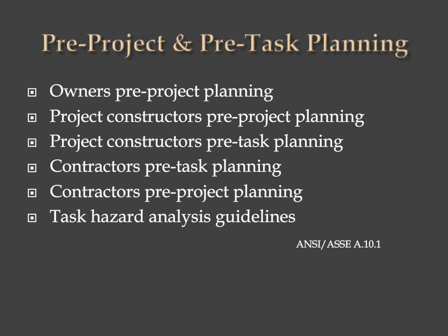And then he's to do a hazard analysis at the initiation of the construction project, and for critical stages of work, a hazard analysis shall be conducted and implemented describing potential hazards, actions required to provide a safe and healthy workplace. And then a meeting of the affected contractors shall be held to coordinate and assign responsibilities for all the items identified.